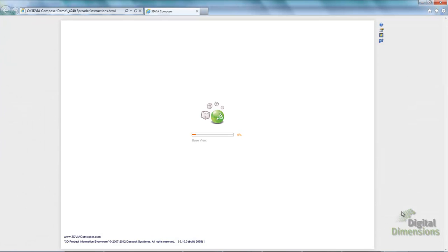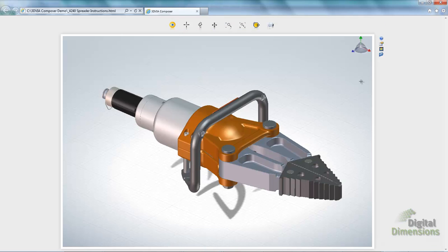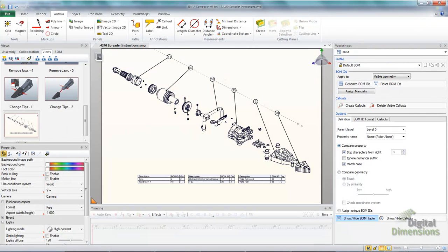And now what you'll notice the moment I get this to load is that I am no longer able to delete an actor. And the big thing here is once you select something and hit the delete key, it just simply doesn't work. There's no command, there's no errors, it just simply doesn't do anything. Okay? So again, this is if I don't want to show the end user what's inside my assembly. I can block their ability to delete the actors, therefore they can only see what's on the outside. Okay, it just gives me a little bit more control over how the end user sees the data.